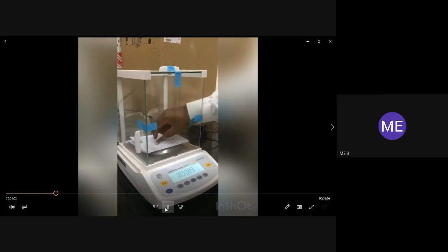So aluminum, first you will take. Why you have to measure is that we require initial weight and final weight. So before putting the specimen in the wear testing machine, you have to note down the initial weight, and afterwards you have to measure the final weight. First we'll take the initial diameter, 12.597. The initial weight will be taken after that. So fix it.